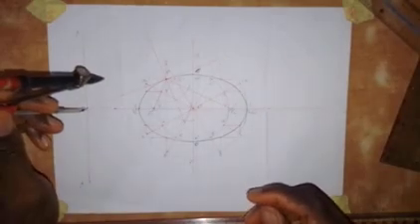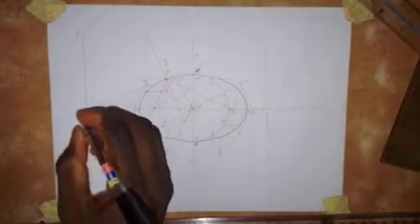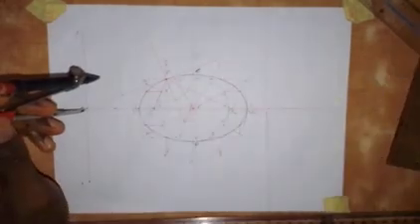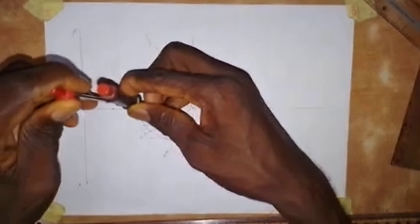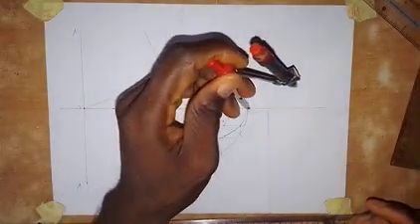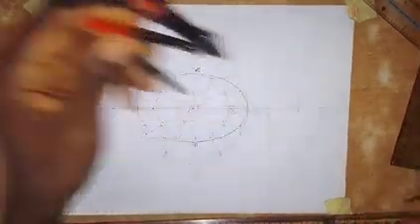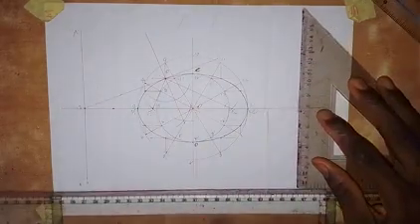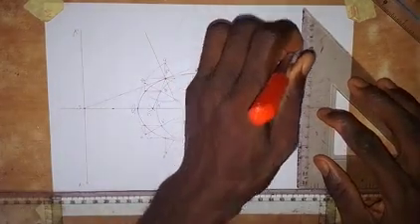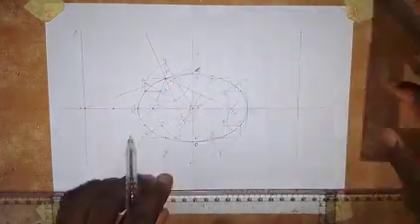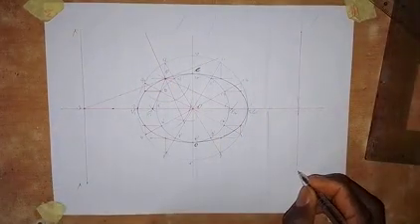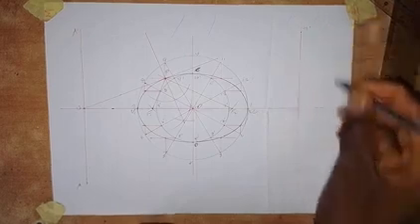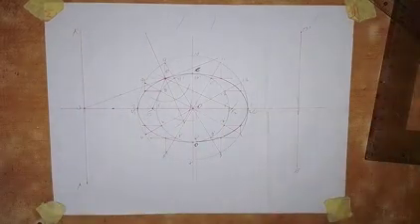To locate the directrix on this side, all I have to do is take this distance from this point. Let me call this point Q. If I take distance Q from V1, then I'll put it at V2 here and make an arc here. This line gives us the second directrix of the ellipse. I'll call this one BB prime. Alright, so we have answered that question in this case.